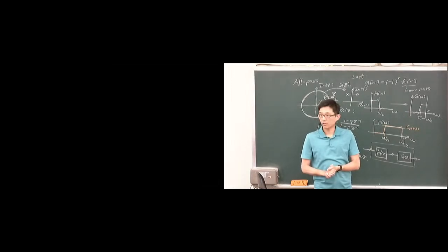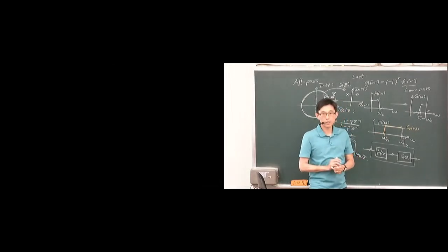When we implement a filter using a difference equation, you can make a system diagram which contains delay, summation and multiplication, multipliers, as well as branching and delay. You can use these building blocks to construct a filter. This new topic is important because then we'll have a more detailed discussion on computation efficiency and so on, FIR versus IIR, in the next lecture.